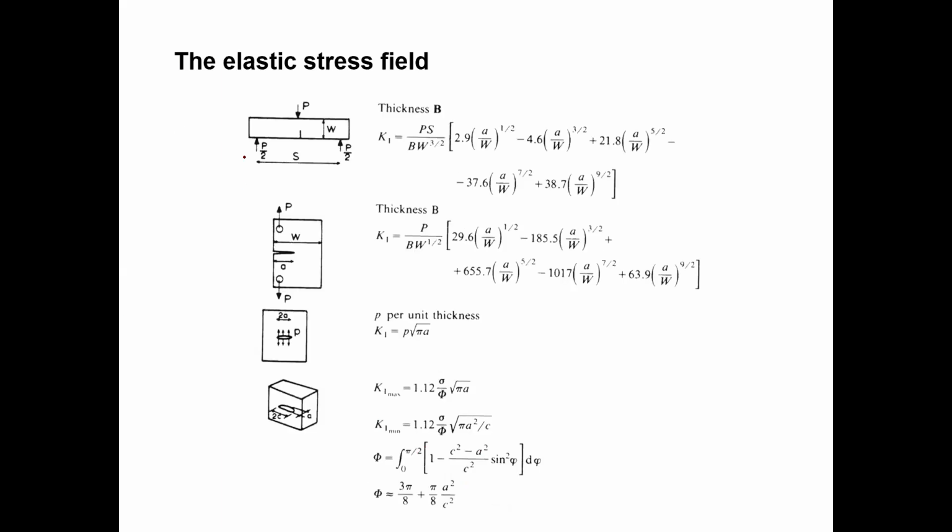And if it is bending, you need to calculate in a different way. So if it is this type of crack with this kind of load, you need to use this kind of equation for K_I. Even though this is tension, it is not applied to the center axis. You can see this is a different loading pattern, so you need to use this kind of equation for this crack type.